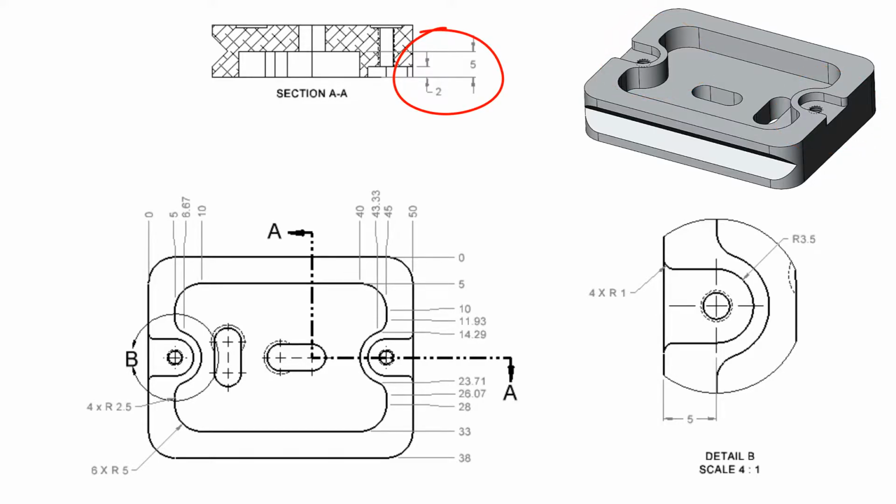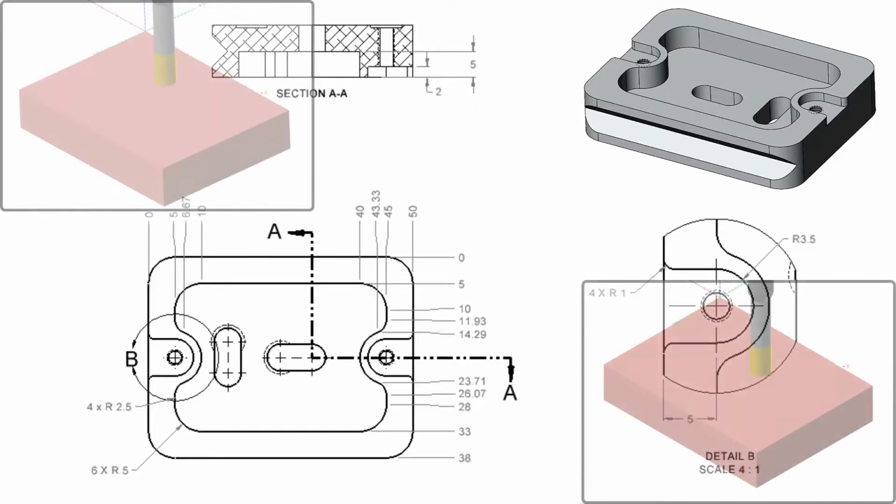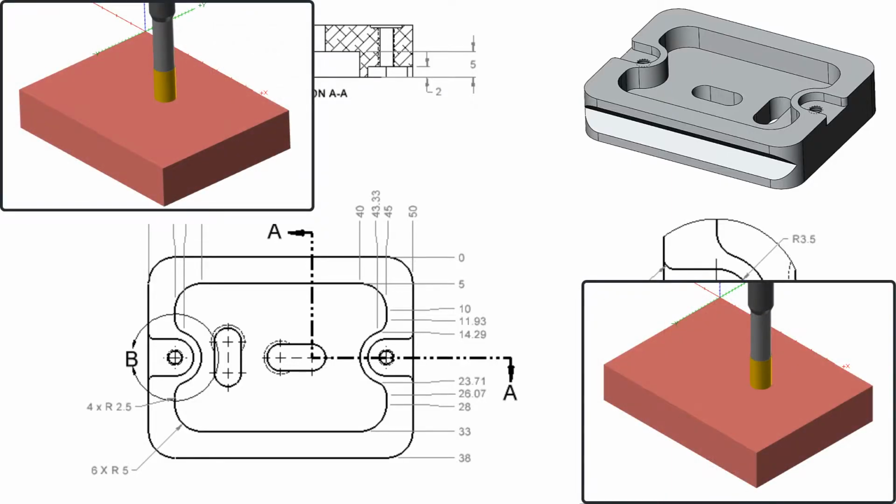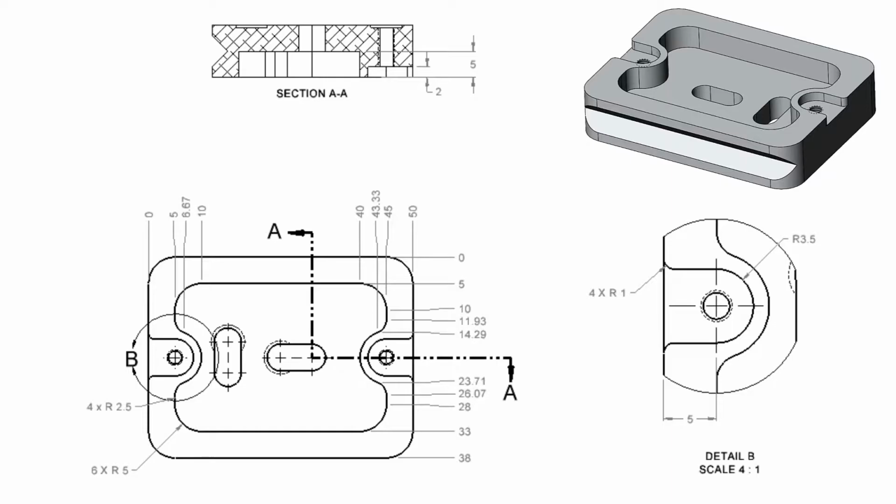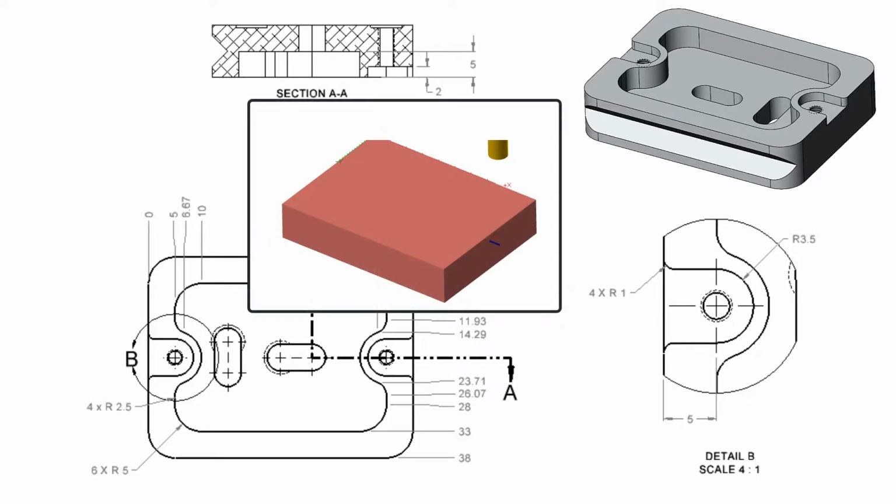How the tool enters a pocket is critical since 100% of the cutter is engaged in the cut unless the pocket is part of an existing cavity, as can be the case with cast parts. As with circular pockets, the tool can plunge into the material, or helix in, or ramp in, or feed into a pre-drilled hole. Since the first two pockets are open on one end, hence the term open pocket, I'll position the tool to the cut depth in the air near the pocket, then feed into the material.